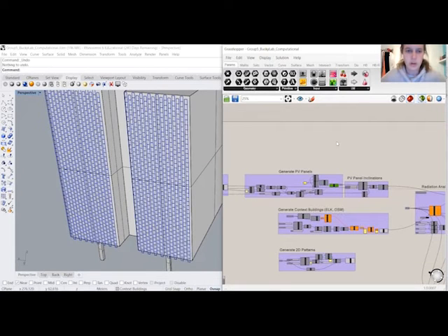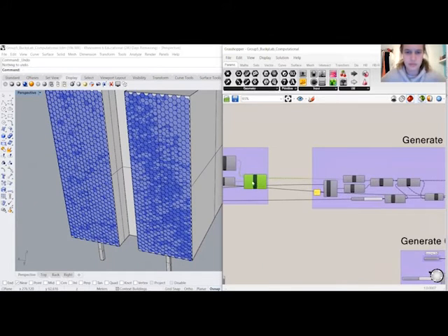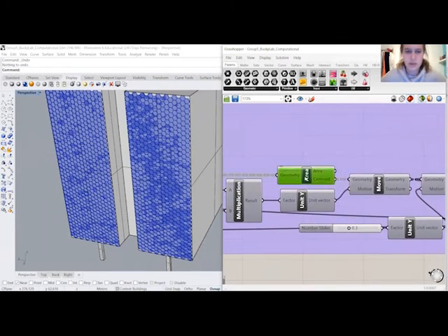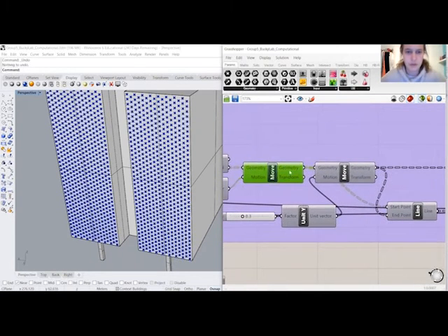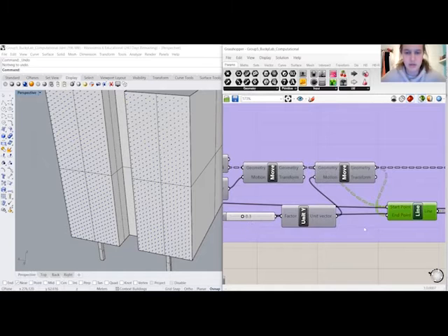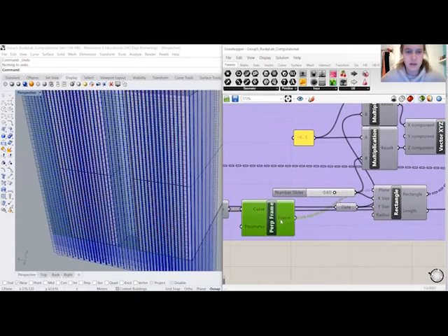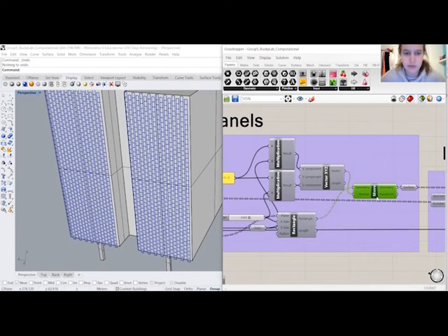Now, how did we draw our rectangular PV on top of our hexagonal green modules? We took the center from our green modules and moved it to the surface of the green modules. From the surface of the green modules, a column extrudes, which is this, by 30 centimeters. Then we drew our PV panels in this frame, but since they are drawn from the corner, we had to move them so that the PV is supported from the center by the PV column support.